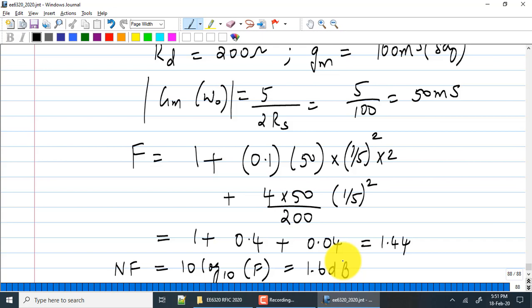It tells you that the noise figure will keep getting lower, assuming that gamma was not scaling. So as you can see, by and large, this would be the most popular LNA for systems that are noise figure limited, for narrowband systems that are noise figure limited.